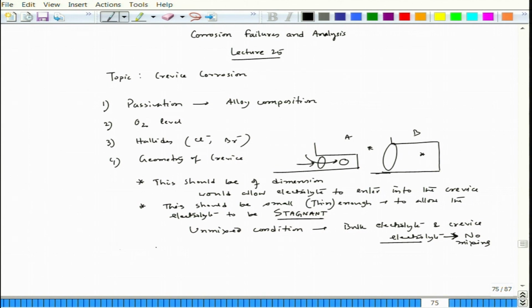Now, 5, if you consider, then bulk composition of the media. Bulk composition of the media, in the sense, I think we should not have that particular same thing separately. This constitutes the bulk constituents composition, bulk composition, fine. Now that could be acidic in the beginning, it could be neutral, or it could be basic. Interestingly, even if it is neutral, we will see that within the crevice it becomes highly acidic. So, we will see that when we go into the mechanism part of it.